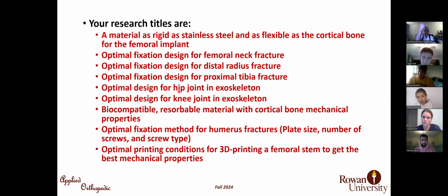For example, consider the elbow joint. The elbow joint is a hinge joint. It has only one motion, flexion and extension. So this flexion and extension can be replicated in the exoskeleton by another hinge. But for shoulder or hip, they move in all directions. So you must have a joint with 3 planes of rotation. And all these 3 planes must have a single center of rotation. Otherwise, they will compress or distract the original joint of the person.